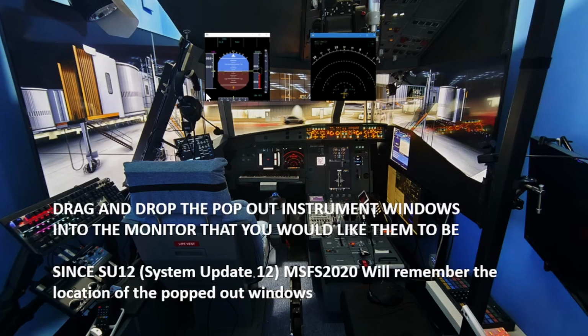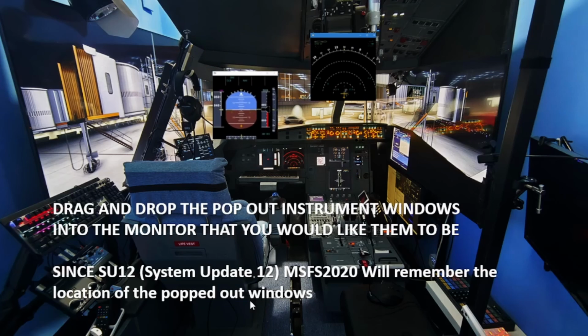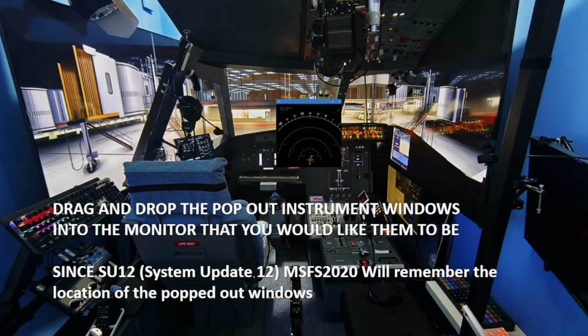So once you pop out like this, you can then drag your display into the right position, try to align it, try to stretch it, try to drag a bit, move a bit. Yeah, it quite takes some time. But after Sim Update 12, I think FS 2020 will remember where the pop-out windows will be. So you don't need to, initially before Sim Update 12, you had to reposition again every time you entered the simulator.